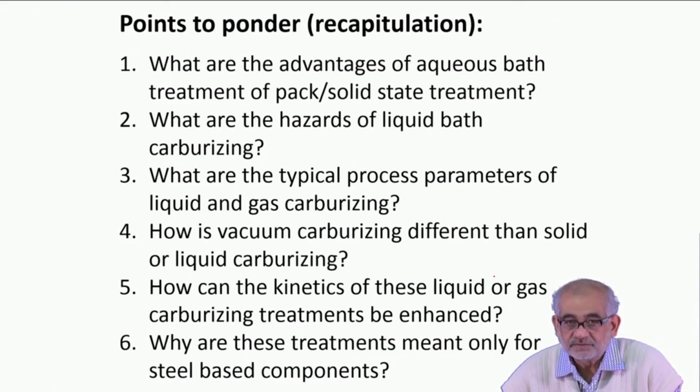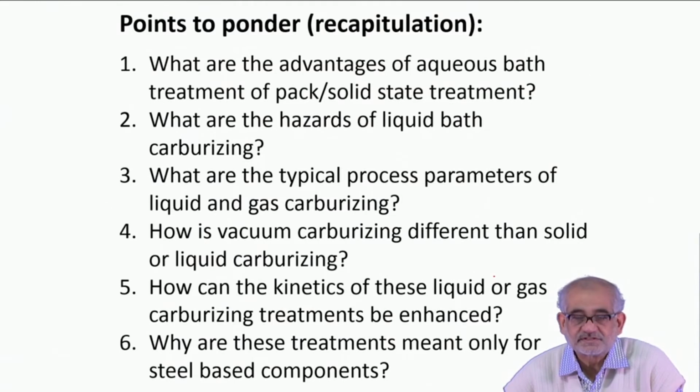Then, process parameter wise, since this is a diffusion control process, all the processes except the initial short pinning kind of processes, all the thermally activated processes are dependent on the diffusion coefficient, the temperature, which in turn governs the level of diffusion coefficient, and then at the isothermal condition, what amount of time we give. So the combination of time and temperature is very crucial. Of course, the activity of carbon either in the solid pack or in liquid bath, salt bath, or in the gaseous state, that's also very, very important. Independently it should be controlled.